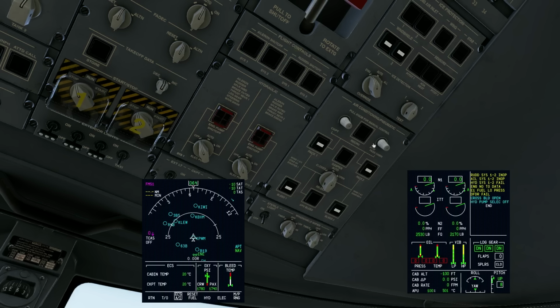And we have a recirculation fan, and we have a gasper. These are the ones above passenger seats, and then this is a recirculation fan. This lets us blend some cabin air that we have back into the system. So essentially this is like that recirculation mode in your car, where if you want to use some of the air that's in the cabin in your air conditioning, then you would use that. Otherwise, if we take it out, we're only ever taking in fresh air. We don't interface with these two too much.